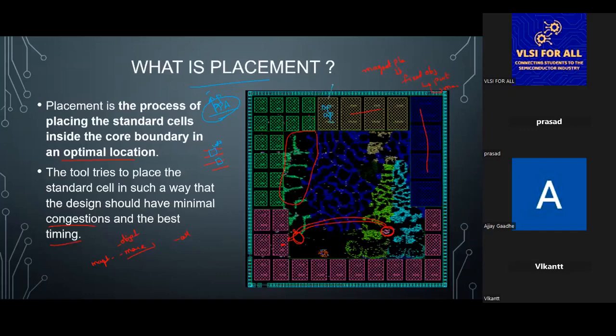So this macro is developed by one more PNR engineer only. He might use the M4 layers, okay, M1 to M4 he might use. So we want to block those on top of the macro. Otherwise, if we do not block, what will happen? Our PNR tool will use them. Okay, it wants to route from here to here. It wants to route with M4.